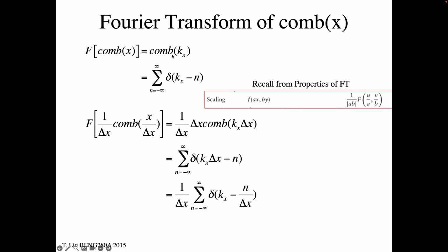And if we want to look at the frequency components, right, we need to look at the Fourier transform of the comb function itself, right? And it turns out the Fourier transform of a comb function, kind of surprisingly, is a comb function. And the gestalt, I don't know how to describe the gestalt of that, but you can imagine that if you need to create a function, so in space, I have this function that is 0 everywhere except these little tiny spikes, I need very, very high spatial frequencies, an infinite number of them actually, to make a spike that is infinitely narrow, right? And so that's why when you get over to the Fourier side, you see a discrete set of sine waves that go into making these spikes, right?